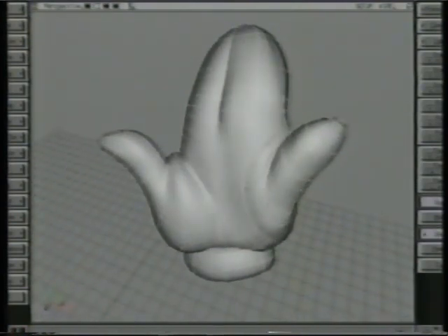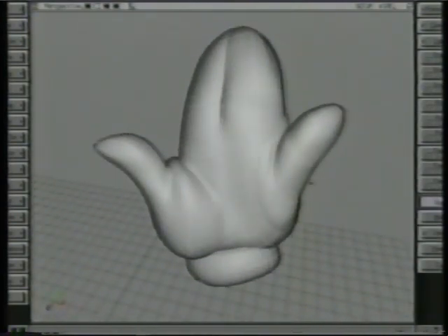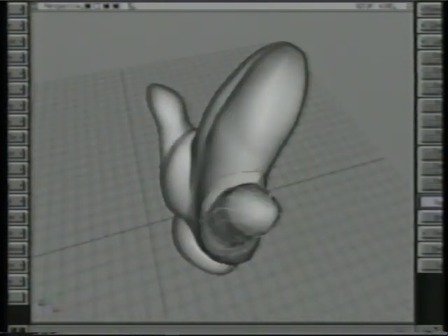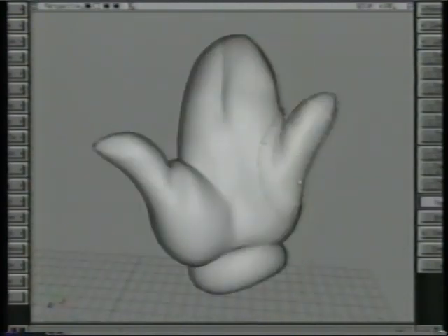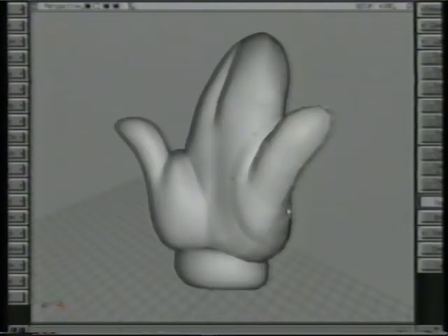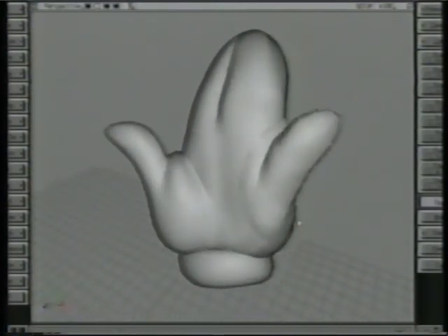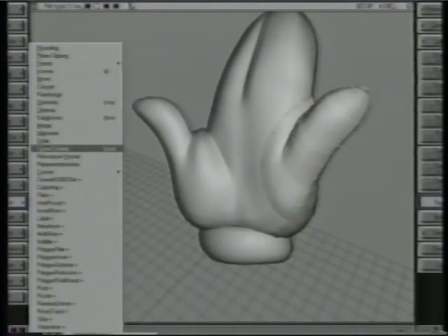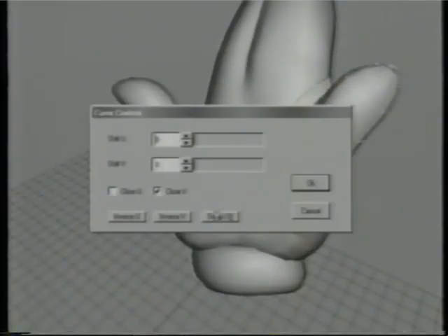Pinky is a separate object. Notice that these are actually inversed. The red should be going up the seam there, and the green should be there for the texture map to lay properly. You can always just rotate things afterwards, but I find it's easier to maintain consistency. So to change this, go into Effect, Curve Controls, and swap the U and V.